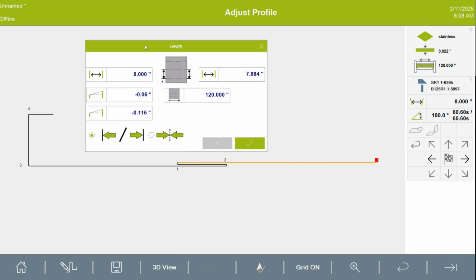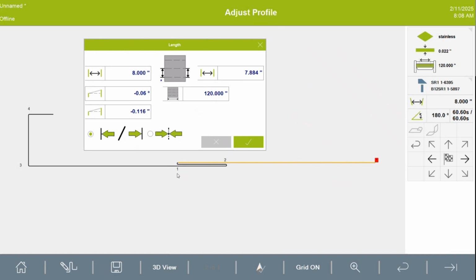Okay, so now let's go to this flange. This one is going to be 8 inches on one side, and it's going to be shorter on the other side so that it can nest between here to here and fit inside of that hem. Okay. So it's going to have to come and wrap over and then go inside and go under and then come back to here. Right. That's what that part is going to look like. Right. So you see it's quite a bit of overlap here. All right.